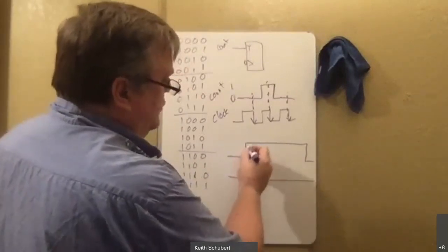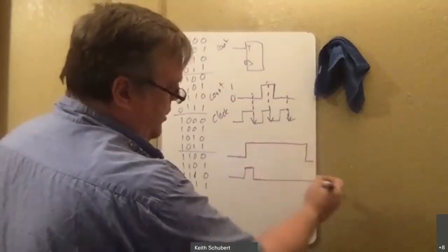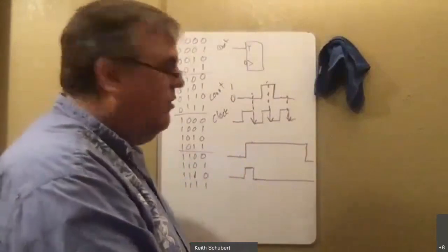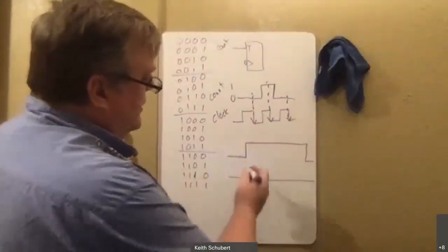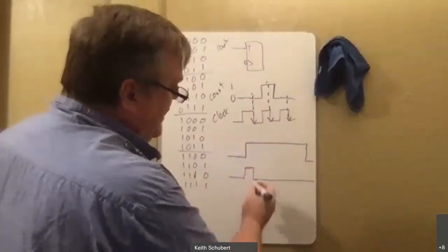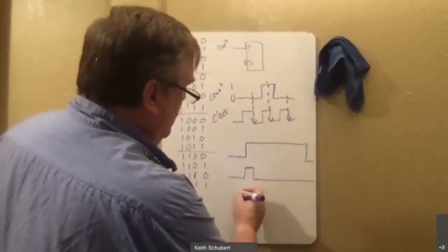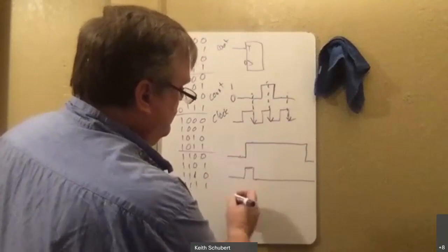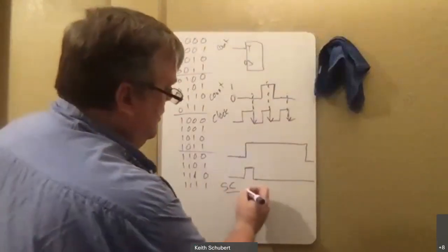So if I just look for the 0 to 1 transitions, I get a 1 here. Since I don't see a 0 to 1 anywhere else, I don't get it. Right? So this is sometimes called a positive slope indicator. It can sometimes be called a positive edge indicator. It's really easy to build a simple version of this where all you have to do, you have your input, this original signal here coming in, my slow count.